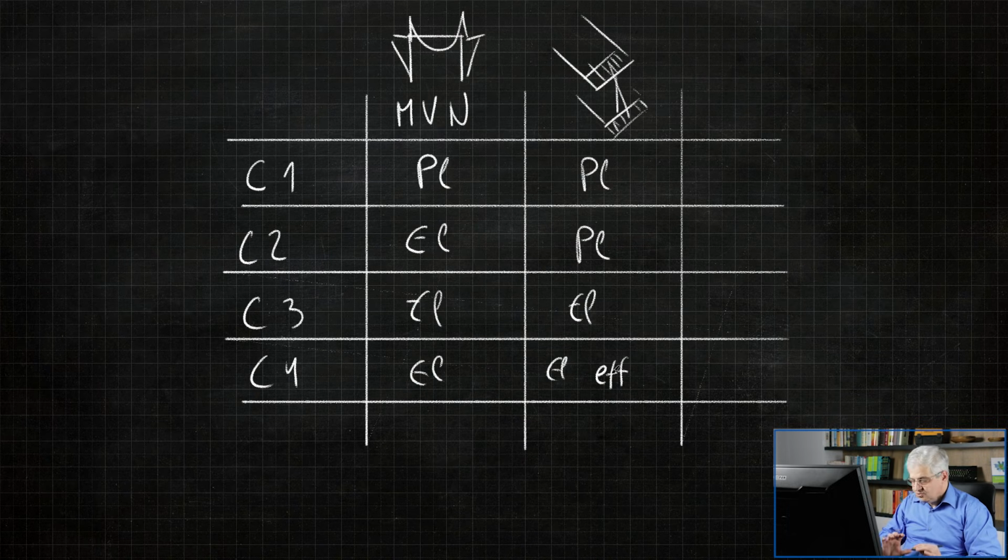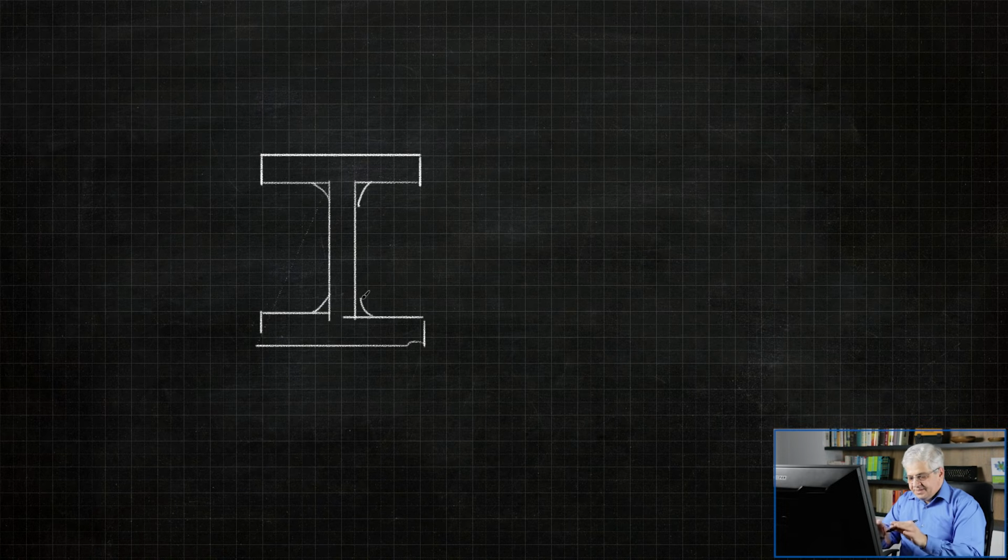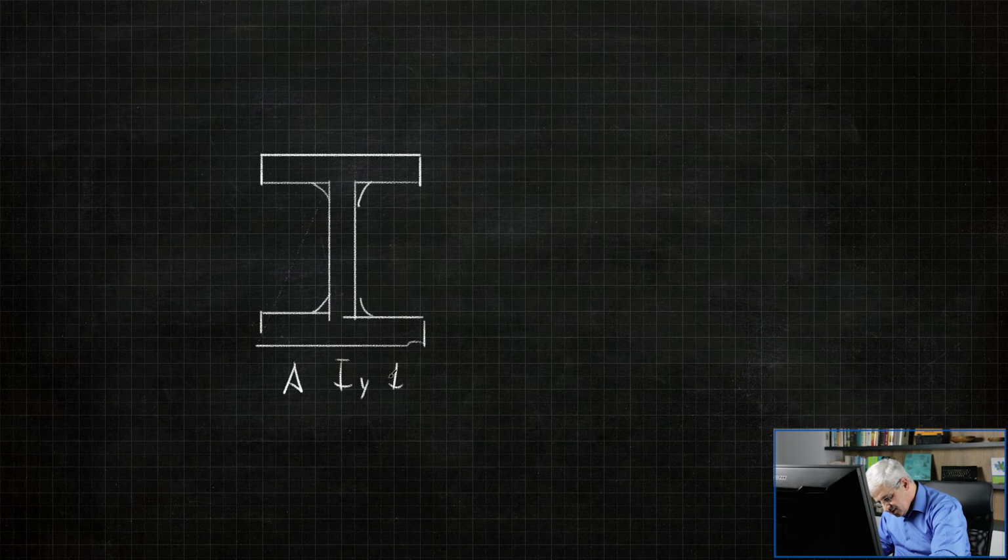So this is the classification in Eurocode 1993-1-1. For us it's important, if we create a general cross-section in SCIA Engineer, to create it correctly, so that SCIA Engineer can classify this cross-section automatically. The cross-section has a standard shape, so let's draw it. I draw it maybe not very elegant. And we have also some roundings or welds. This shape is used for the calculation of cross-section characteristics: cross-section area, torsional constant, and so on.